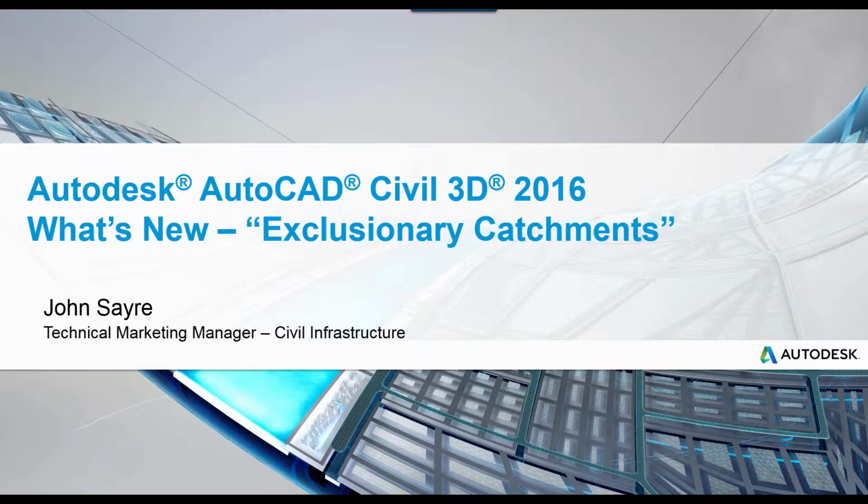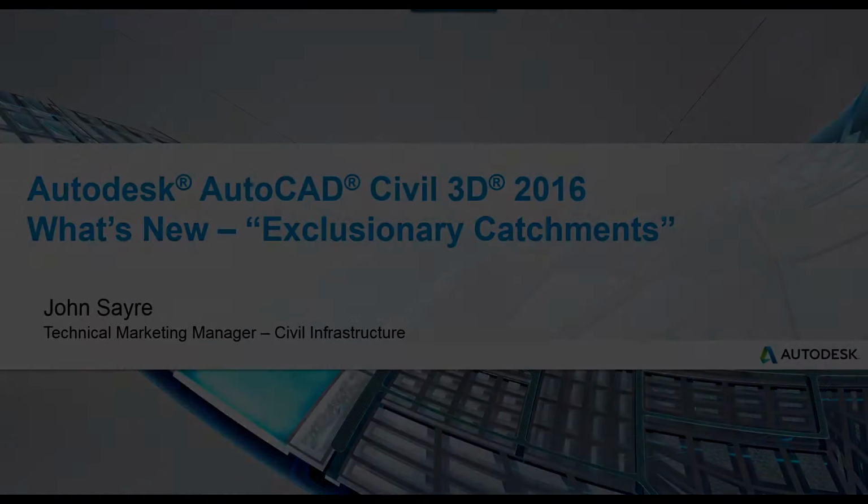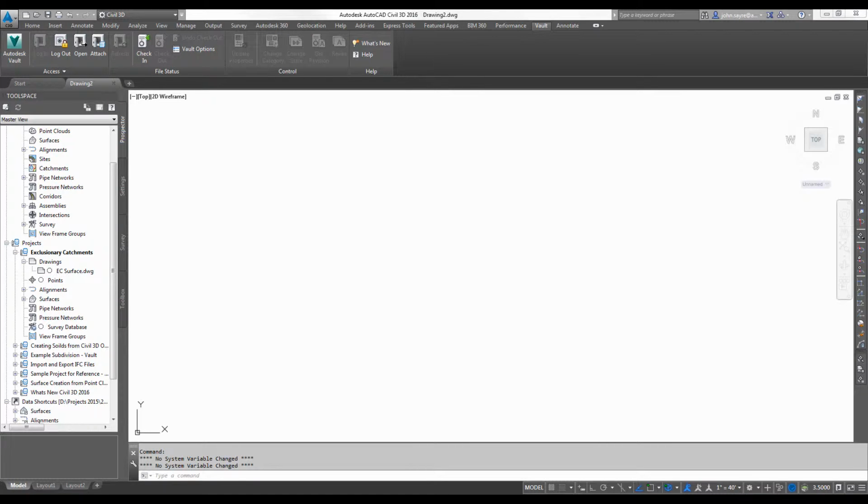Today I'd like to talk to you about one of the What's New features in AutoCAD Civil 3D 2016, using exclusionary catchments. So what are exclusionary catchments? If a catchment is exclusionary, its boundary and flow path can be modified either by existing catchments as it is being created or by new catchments as they are being created.